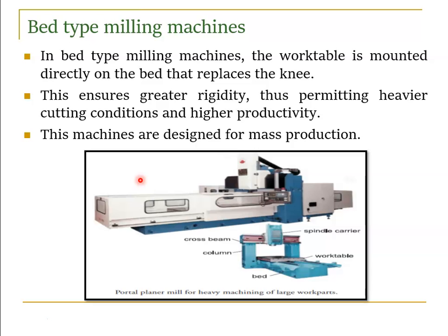So this ensures greater rigidity, permitting heavier cutting conditions and higher productivity. So for heavy cuts or higher productivity, we go with bed type. These machines are designed for mass production. So for mass production we use this kind of machine.